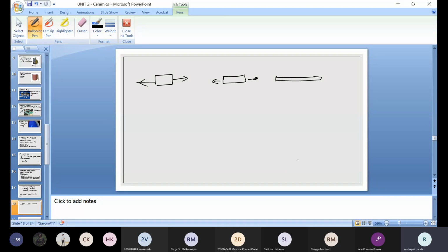So in this particular glass drawing process, which type of thing will we be able to make? We will be able to make long tube-like structures, like the tube lights we use, right? The glass tube we use in tube lights is made by this glass drawing process. Okay, so there are two methods by which we can get the drawing process done. One is applying the tensile force. Other than that, we also have a process where we push the material through a small nozzle, so that we get the wire. Okay, that is another type of glass drawing process.